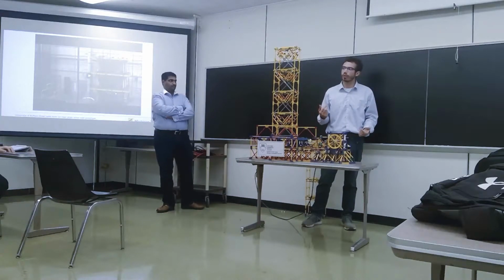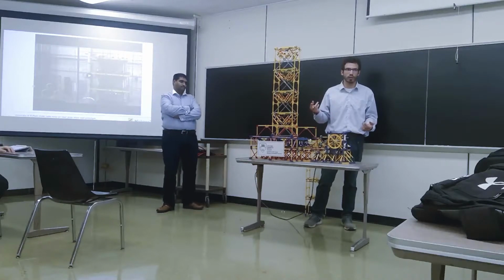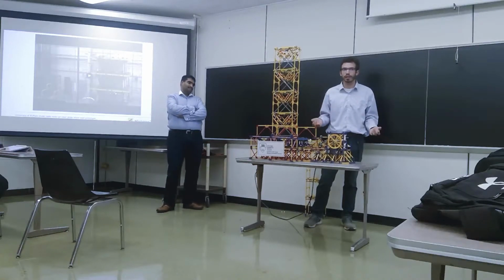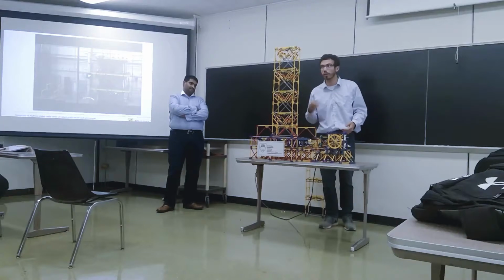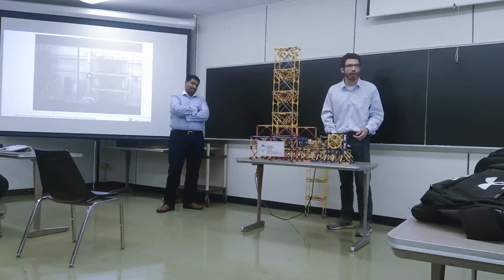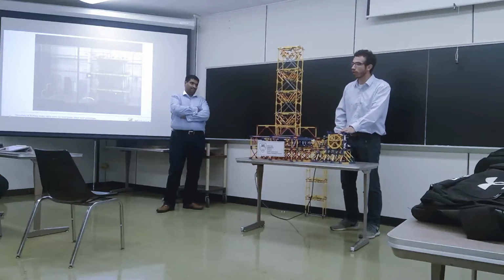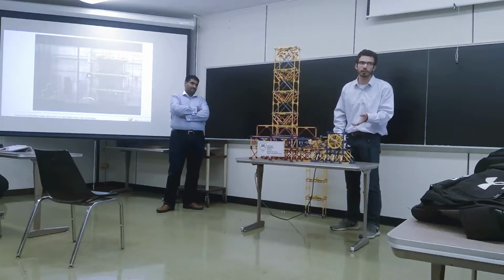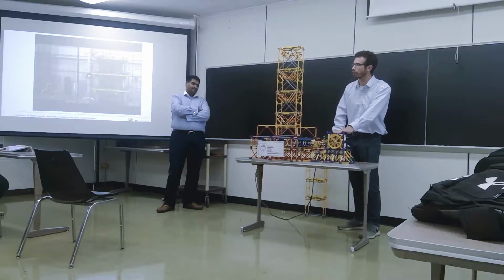So there's a phenomenon with braced buildings like this called period lengthening. It's essentially the building getting damaged. So I'm going to try to show that. We'll see if I can get it to happen. So first of all, I need to get it to its resonant frequency, which is going to be pretty high.